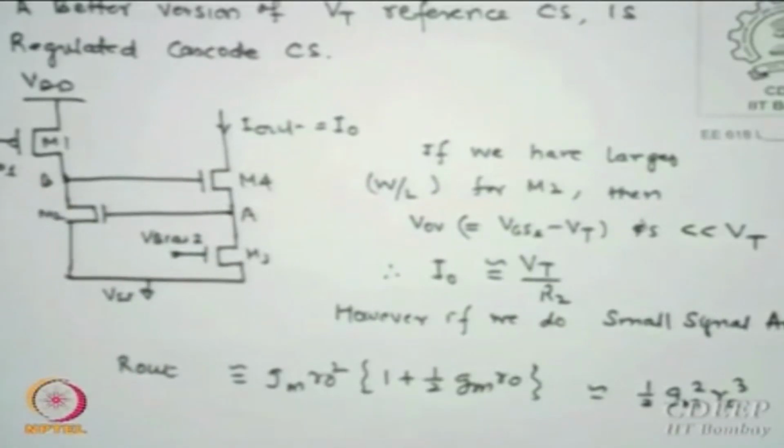This is like a cascode. So what is the advantage of this circuit? Output resistance is boosted up. One of the major requirements of a good current source, last time someone was asking what is a good current source. The question asked was whether it is temperature dependent, how small is the temperature dependence, how large is the output resistance, and how much it depends on VDD variations. A good current source should have lower VDD variation, lower temperature variation and larger R0. Those are called good current sources.